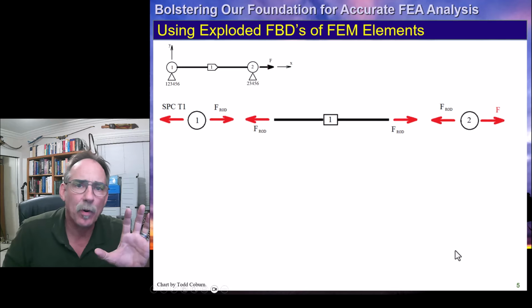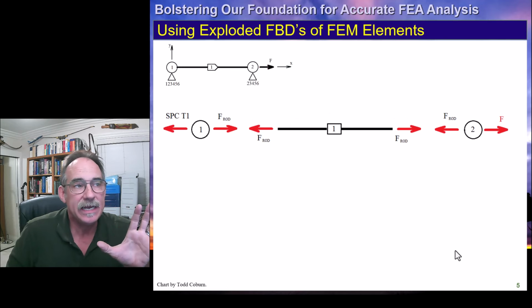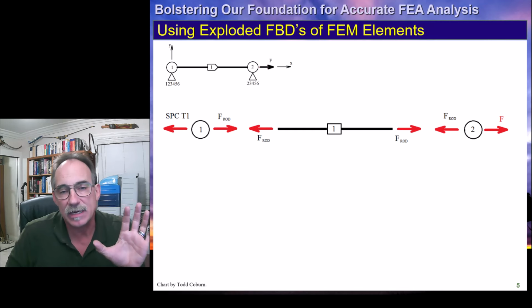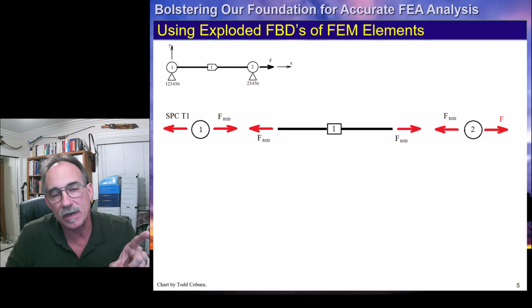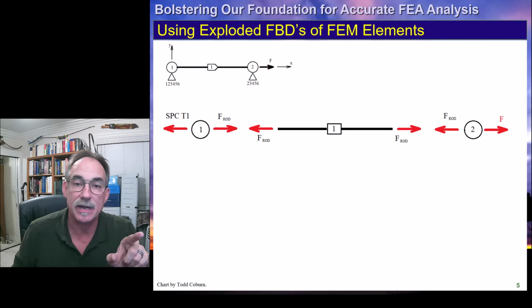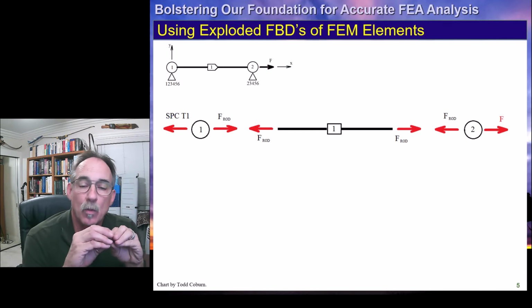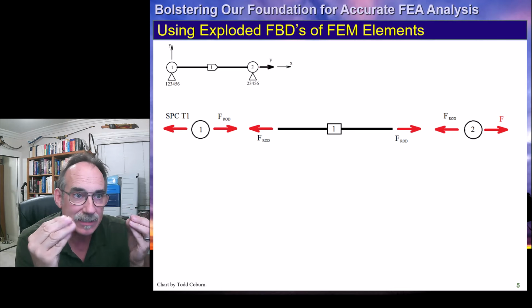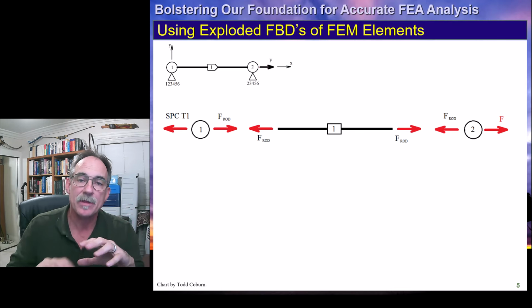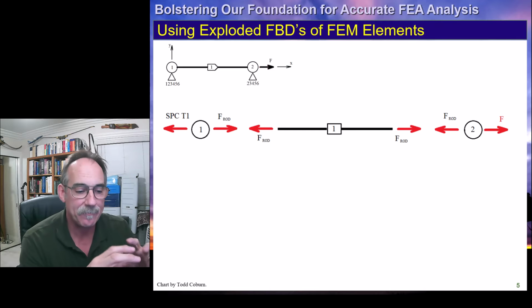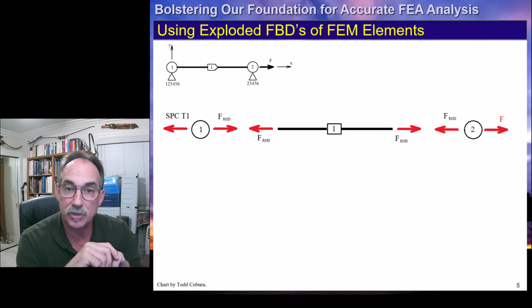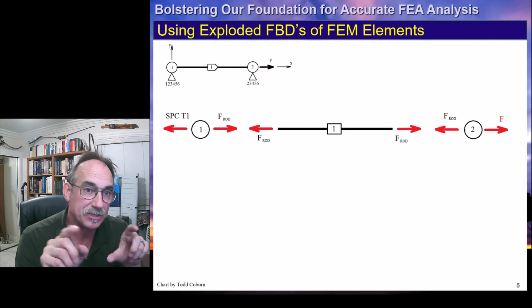So another practical skill that we need to start with at the lowest level is making free body diagrams. One great free body diagram is for understanding your NASTRAN results, and if you start with these little verification models first and practice making a free body diagram, you then can expand upon that. It will give you experience for making larger and larger and pulling substructure free body diagrams, and so forth.